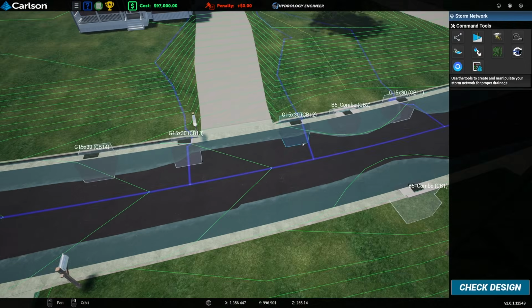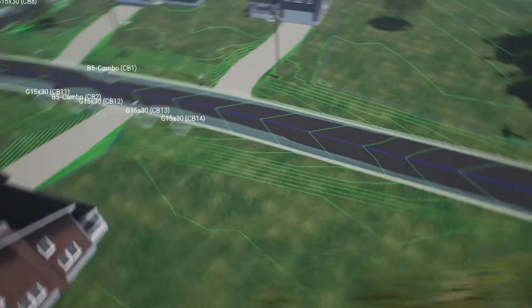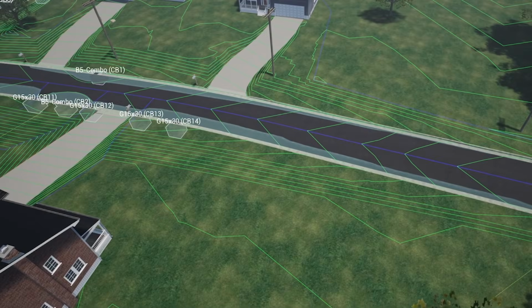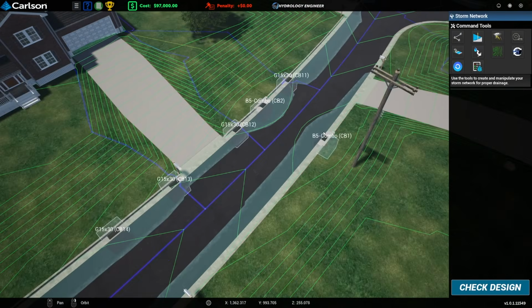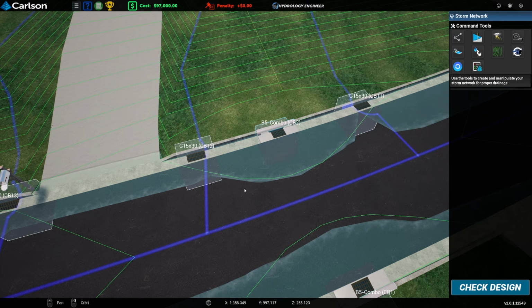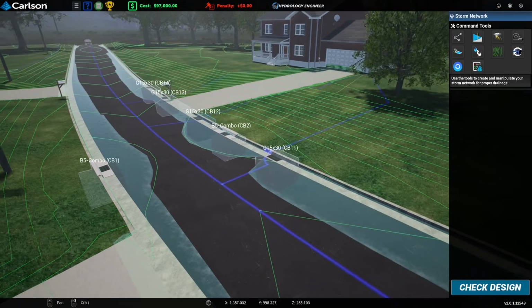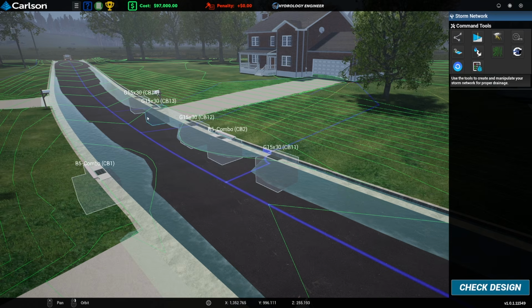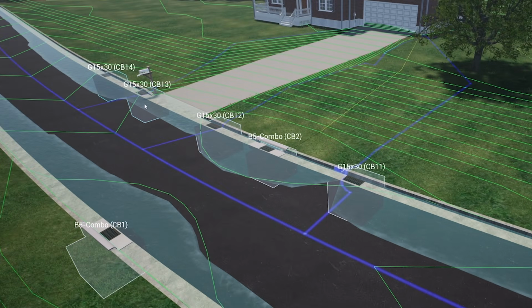And those with a keen eye may have noticed, in the real world, you may have seen gullies generally spaced fairly infrequently, quite far apart, but then you may see a little area where there are loads of gullies close to each other. And that's pretty much how you can spot where there's probably a low spot. And rather than just a low spot, it might be a flat spot. So as your road gets flatter rather than steeper, you're going to need more gullies because the water isn't going to be flowing as fast.